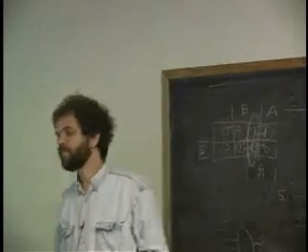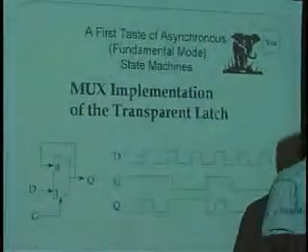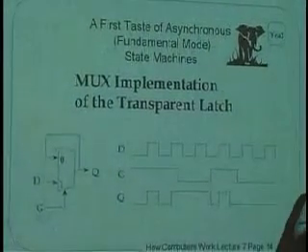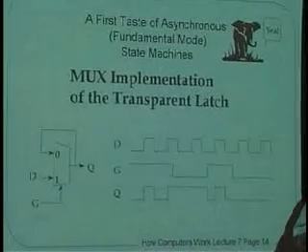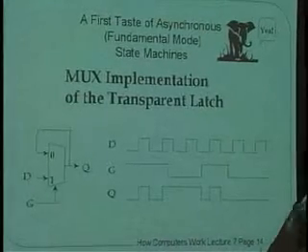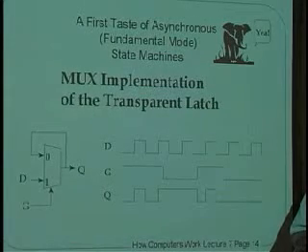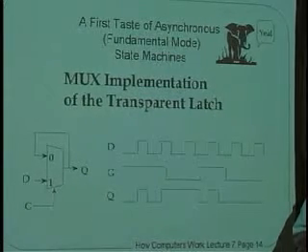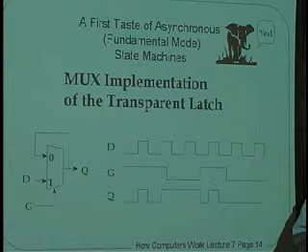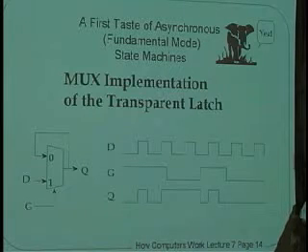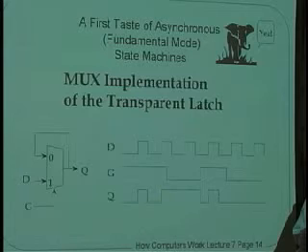Okay, cool, huh? So now you know how to build a latch out of gates, which is pretty neat. In future classes, we're going to talk about how to build gates out of transistors. But for now, what's the latch used for? Well, in this case, it's just used for storing things. Just memory? Just for memory. And it is sort of the most primitive kind of memory. But in a few seconds, we're going to show how to take a latch and build a flip-flop out of it, out of 2 latches. Okay?